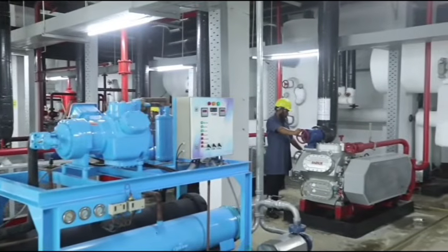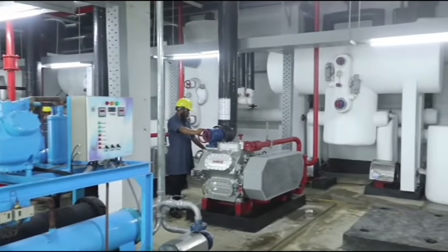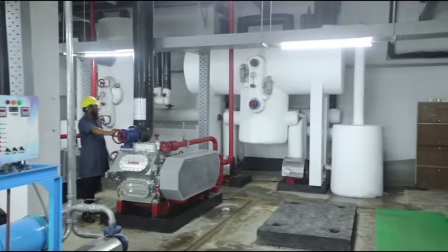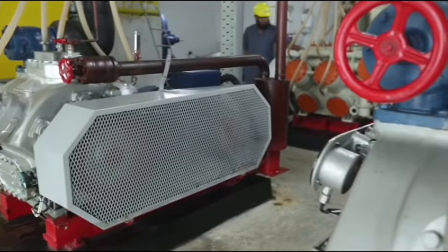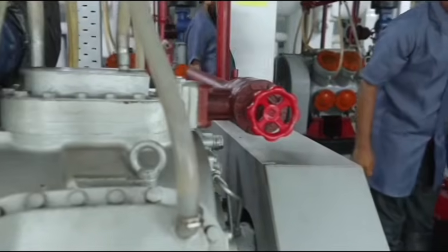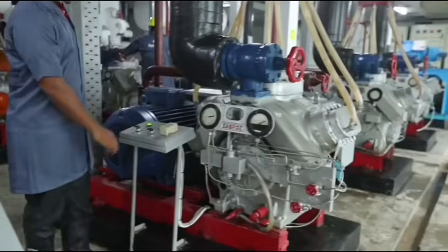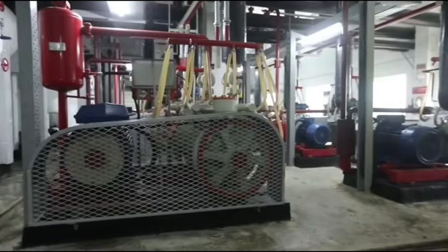I mean, they are not conducting the root cause. They are not taking the preventive measures for recurrence of the frequent formation of ice on cooling coils. Uncontrolled humidity can have big effects on a wide range of operating costs. Ice forming on fixtures and equipment, blockage of evaporators, mist forming in the air.